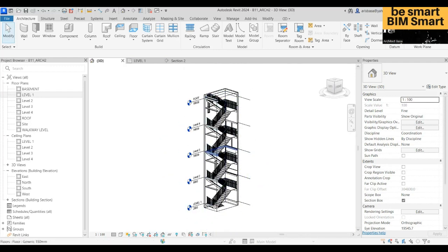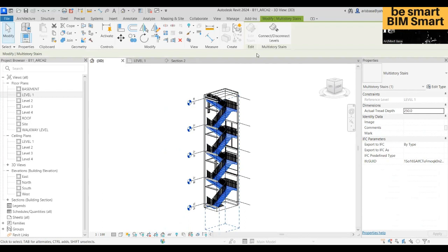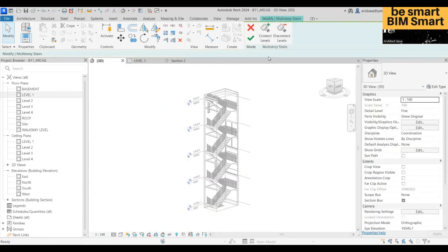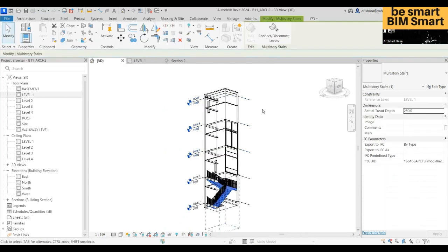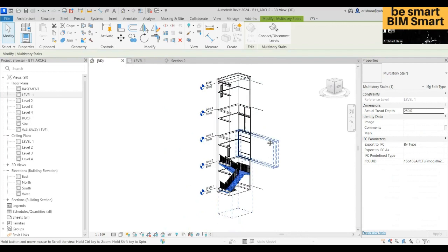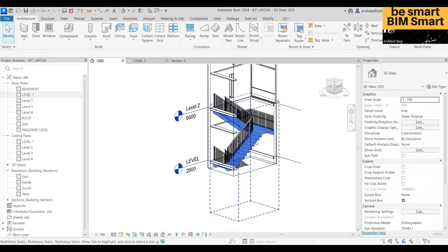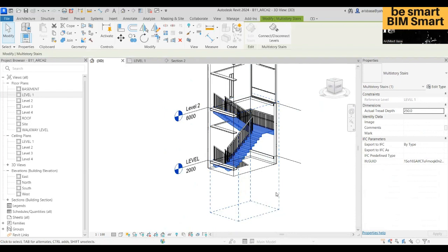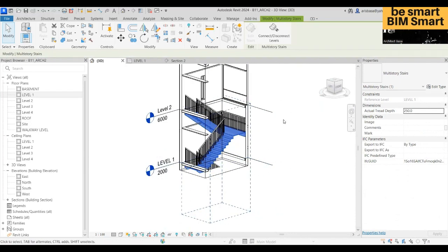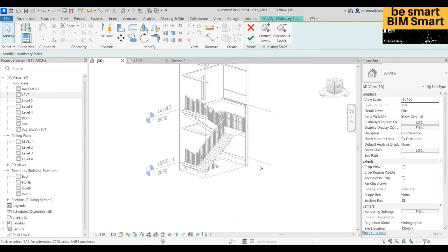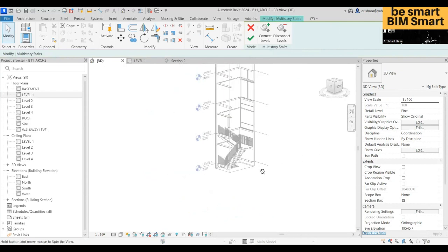So what happens with like this is you select the entire staircase and you connect and disconnect the other levels. So let's say you disconnect the levels, this and this. You can actually do it just like that and check. So those are disconnected, so it's not adjusted there. You have only one staircase now. So seems like it is now possible to change the type of stair. There's still, okay, let's disconnect one more. Disconnect level. There's no more, right?